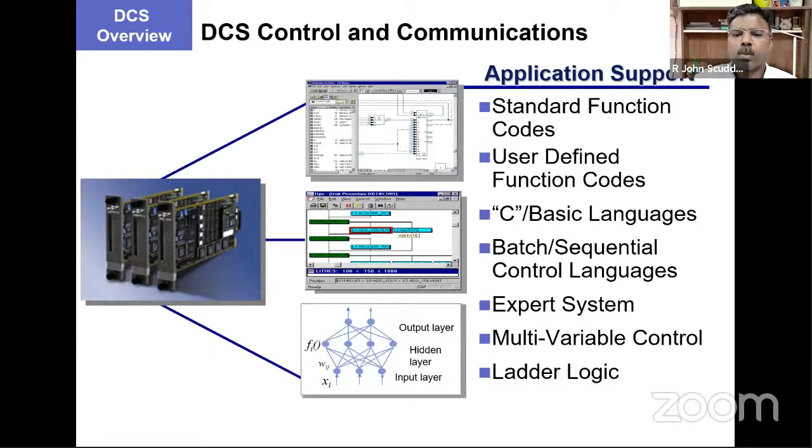In DCS, one very interesting thing is that many are already tailor-made standard function blocks. Imagine you want to start a pump. There is already a block which will receive the on-off input of the pump, and that particular block will be able to issue a start or stop command.